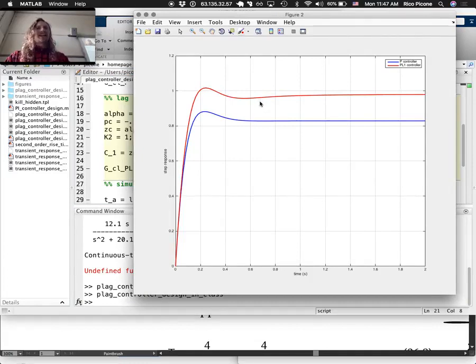Our settling time, so there's a little weird thing to observe about settling time. Typically, the definition of it gets really messed up when you use this slow steady-state error compensation, using an integrator or using a lag compensator, because the definition of the settling time is the time at which the response gets to within 2% of the final value and then doesn't leave it again.